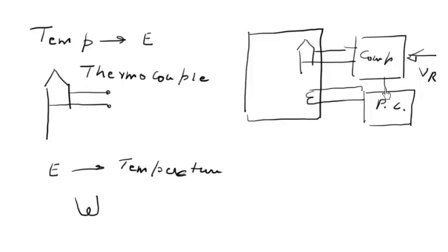So if the temperature rises above the reference value, this information will be provided to the power control unit and it will reduce the current through the heating coil, bringing the temperature to the original value. On the other hand, if the temperature drops, then again the comparator will generate an output signal and the power control unit will increase the current through the heating coil so that the temperature will rise to its original position. So this gives you an example of the use of temperature transducers.